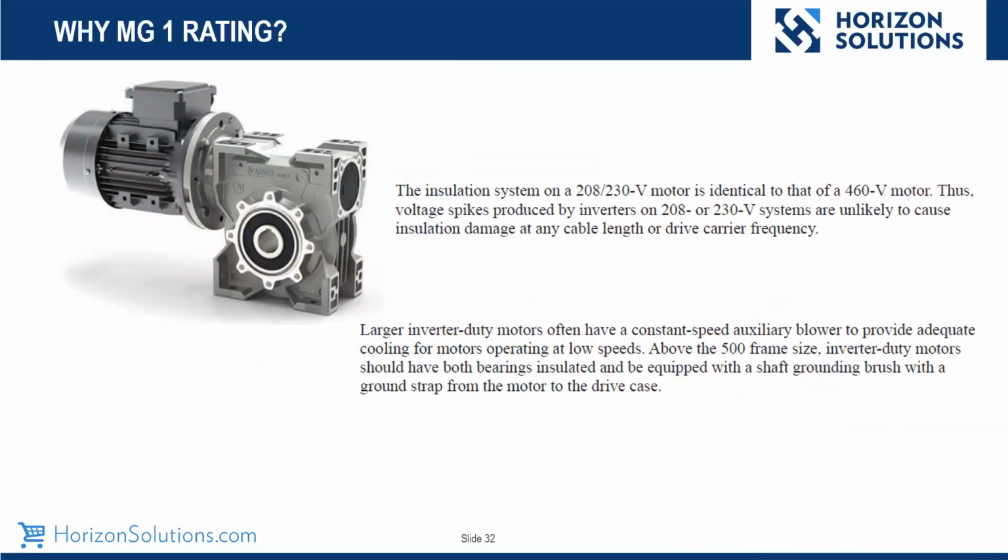We all get asked this question a lot as VFD specialists. Hey, I've got a 230 volt or a 208 system, and I'm worried about reflected wave. Well, the motor construction for the MG1 motors is rated for the 460 volt motor standards. So this is not a predominant thing unless you get over a couple of thousand feet, and then give us a call. We'll discuss it with you, but this is really not the phenomenon with reflected wave at the 200 volt level. At 400 and 500 or 400 and 600 volt, that is an issue.